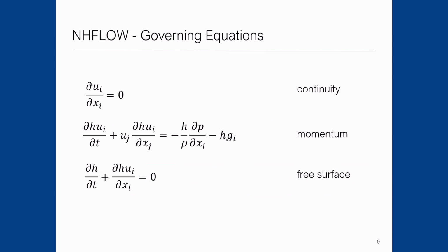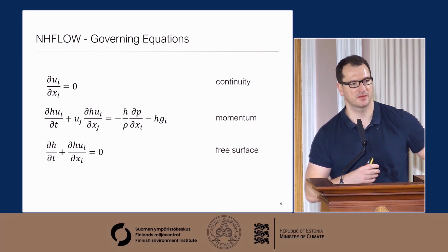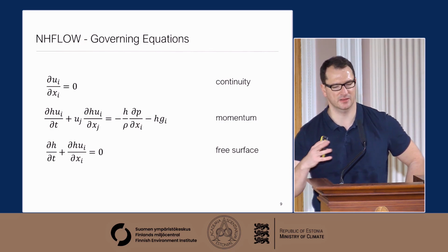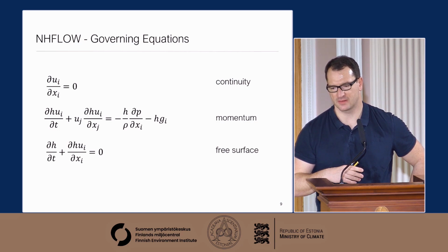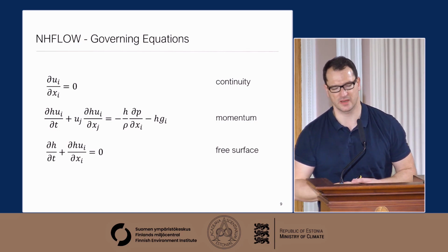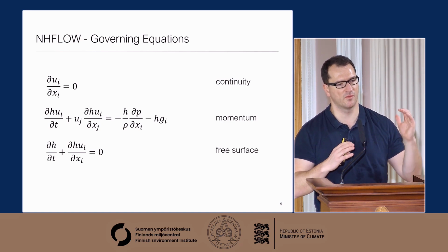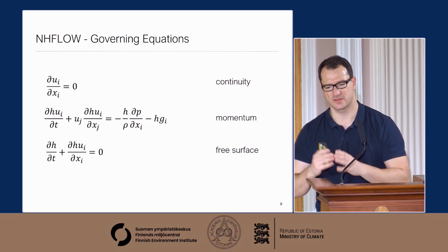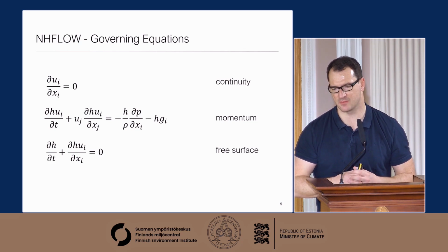Yeah, I'm just showing here the governing equations. So for this new model, NHFlow, a non-hydrostatic model, we're solving the full Navier-Stokes equations, continuity, momentum, and then the free surface elevation is being calculated by integrating the continuity equation over the depth. And this is maybe in contrast to what we can do with the high-resolution CFD model, where we can look at two phases. We can look at the overturning crest of a breaking wave. With this type of model, that is not being directly captured, but we can represent kinematics of a breaking wave.